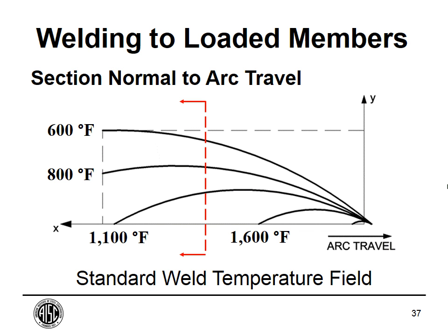But to answer your question, I don't know the answer, but I can tell you that it depends on the distance from the weld. If you're a foot from the weld, it'll be cool to the touch in a lot of cases. It depends on the heat input. For stick welds, like I do as a hobby, you can touch it a foot away just a few seconds after or while you're welding, basically.